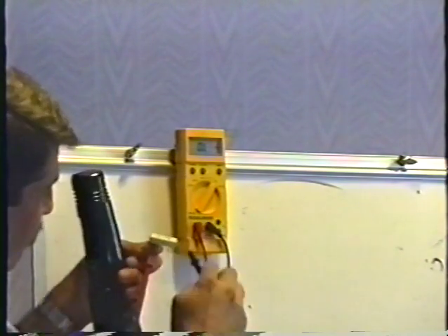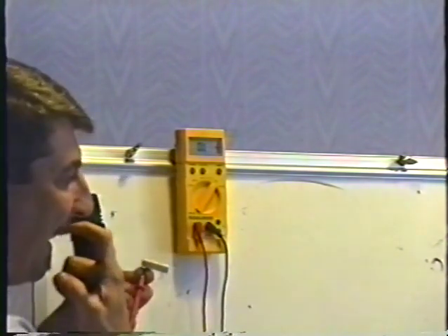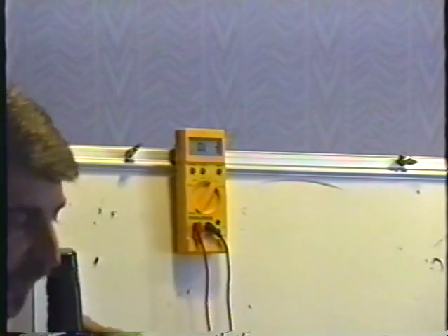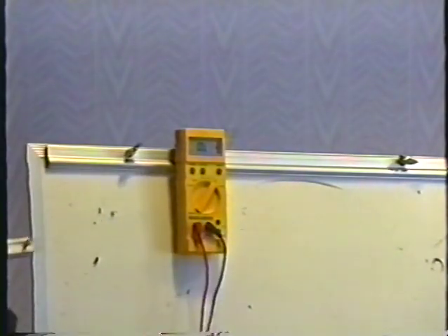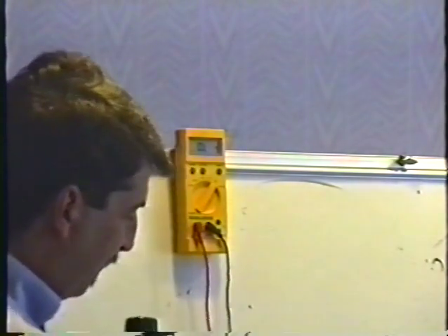It's supposed to be 2 ohms. It says 2 ohms on it, but it's open. And it even says on the back of it, open. So always pull your resistors out. If they say open on the bottom, they're bad. This one also says open on the bottom, but obviously I wrote that on there.